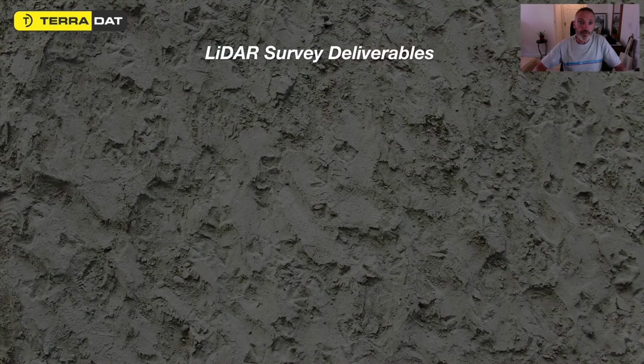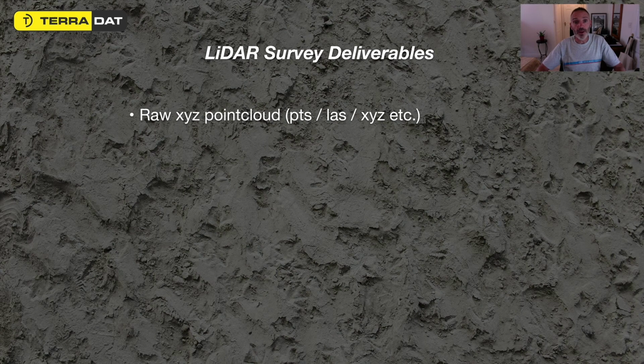Okay, so we've completed the survey on the beach, we've downloaded the data from the laser scanner, and then we've registered it in the proprietary scanner software. Now I'm going to run through some of the common deliverables and talk about how we can present LiDAR data. The first one, which is the most basic, is a raw XYZ point cloud.